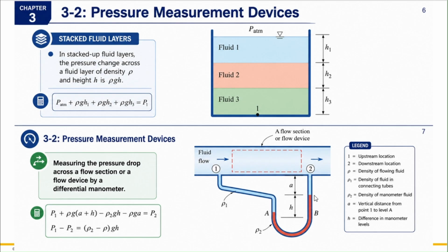Now it doesn't stop there. That is the pressure at this particular location, and it should go further upward. If it has to travel further upward, we need to subtract that much pressure, which this time is the density of the water, rho times gravity times a, and that's what this particular term does. So that collective arithmetic operation gives you the pressure at point 2. It's that simple.